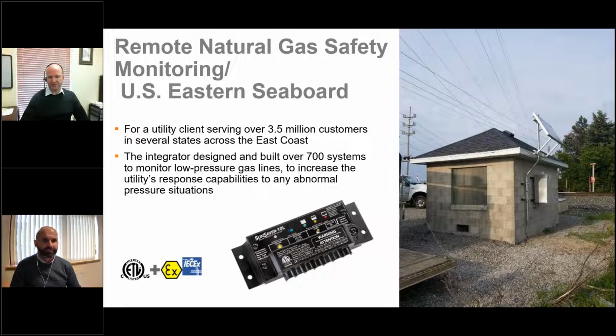A couple of other applications here, I'll just touch on them briefly, not so much case studies, but to show the diversity of the different types of systems that get used. Our SunSaver product, one of the most popular and typical in these types of hazardous locations, is often used for natural gas as well. And simple monitoring is really critical. You've got these handoff points or small shelters built where there are some valves above ground, where there's control or transfer of assets, and they need measurement capabilities. It doesn't take a lot of power, but the RTU's job is extremely important. So just a simple module such as the one on the roof there, just one of them, and a SunSaver 10 gets the job done.